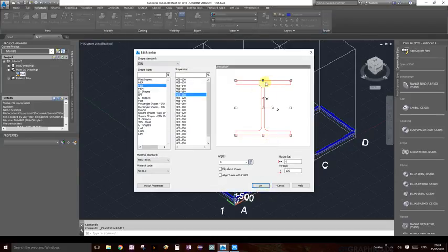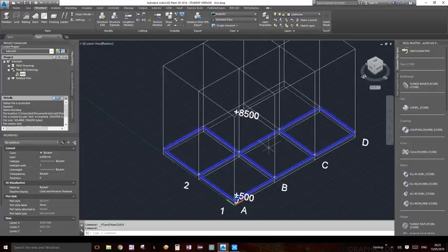So it saves a lot of headache to just go ahead and do that. What I've done is clicked on structure edit from modify, and now I have, as you can see, that little blue dot. I just put it on the very top middle. Press OK, and then we're done.